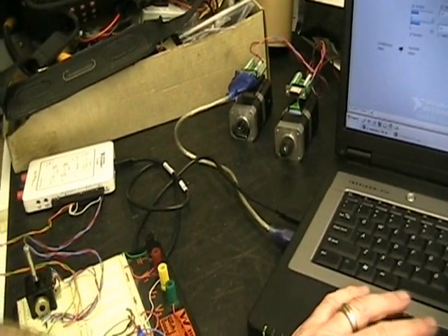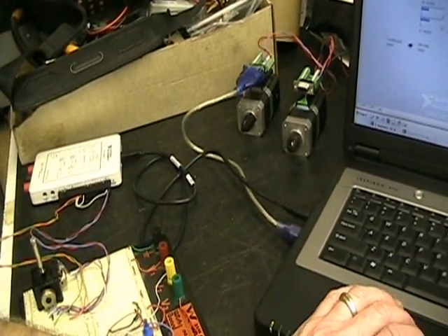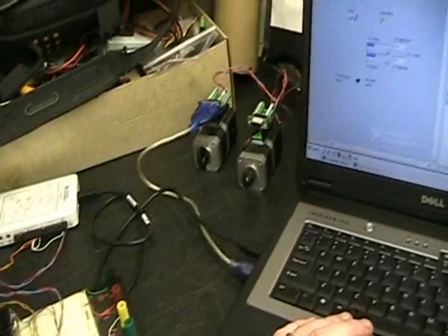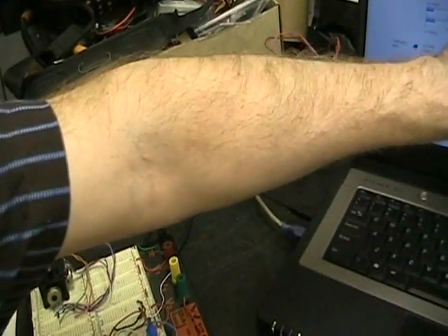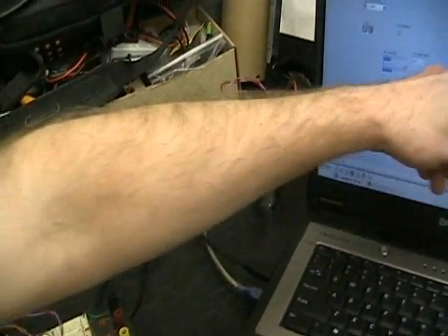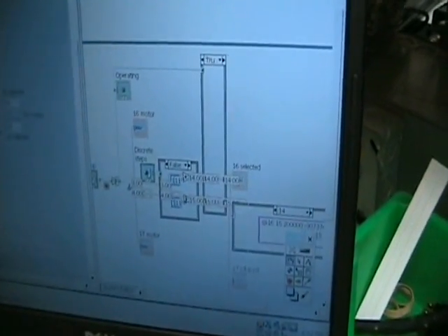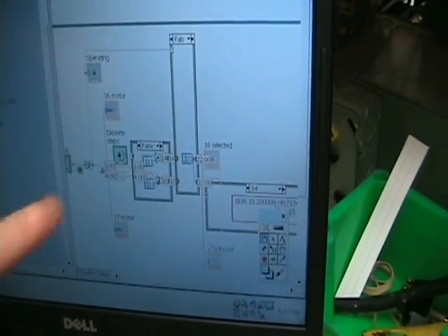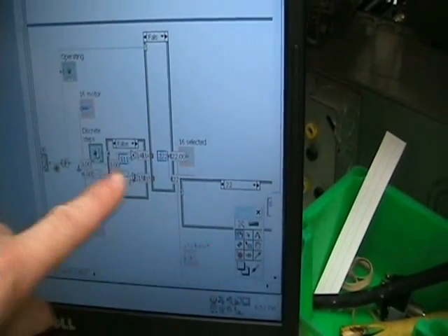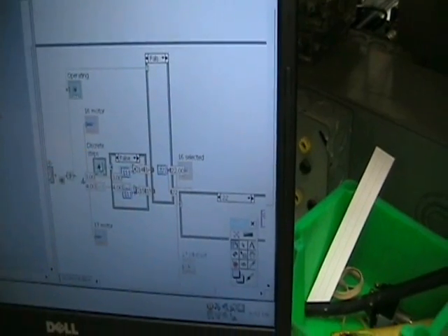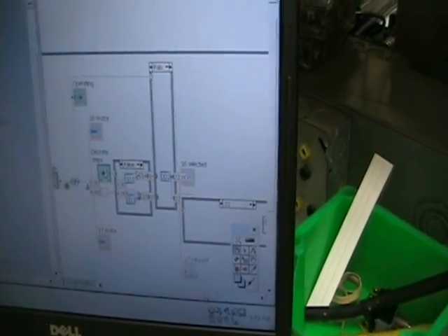There's one other trick. In this continuous mode, you need a stop command. If I hit stop, it clicks this guy into, oh, there it goes. That will send out a 22 from here, which overrides the inputs from the joystick.